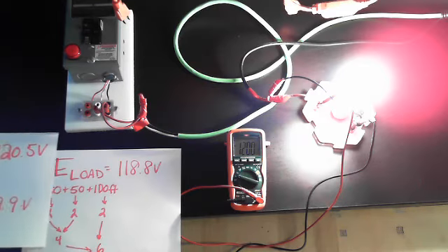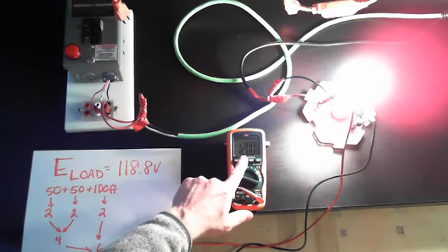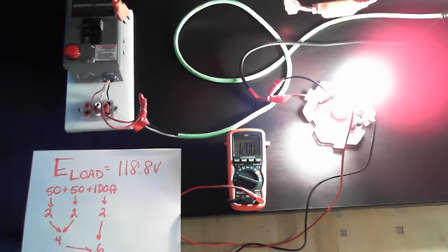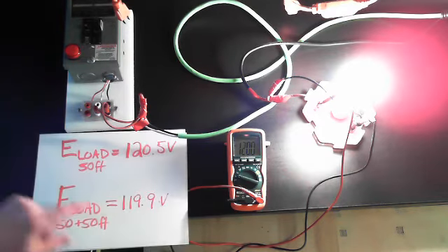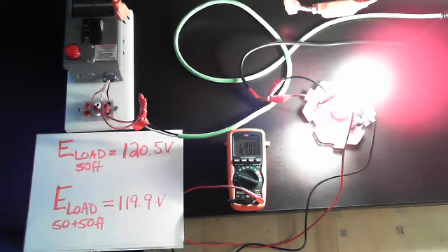With half the length of conductor, with only 100 feet, we have 120 volts, versus 200 feet, we have 118 volts. With half of the connections, right, we have 4 connections here, versus now we only have 2 connections. Okay, so it looks like the length of the conductor is really the thing that's governing, the main significant piece of voltage drop. Conductor length, right, is a big thing. Primary driver. The number of connections have a bearing on that.